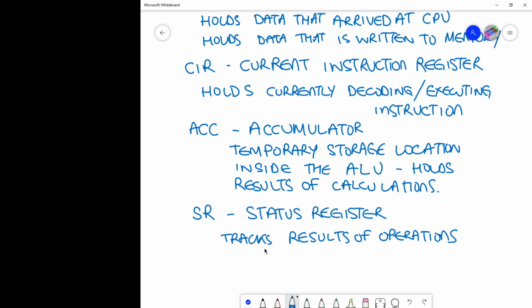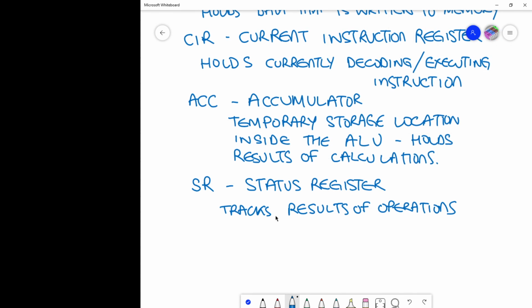You don't need, I'm saying don't need to remember, but I want you to remember. No bonus marks for this, but condition code flags. The N, Z, V and C. So negative, 0, overflow and carry are the main ones. There are others, depending on what CPU you're messing about with. You can have like half carry operations and all sorts of weird things. So you can tell whether you've carried from one nibble to the next, which is actually quite useful sometimes. Okay, so 18 potential marks there.